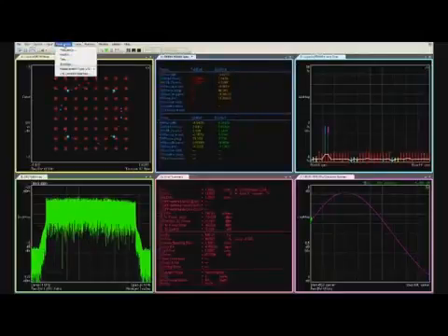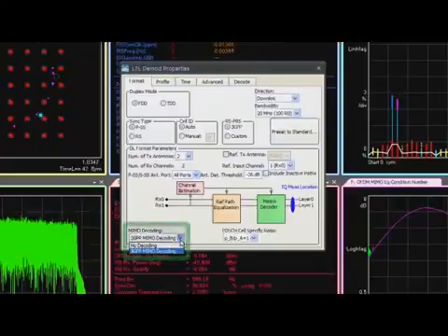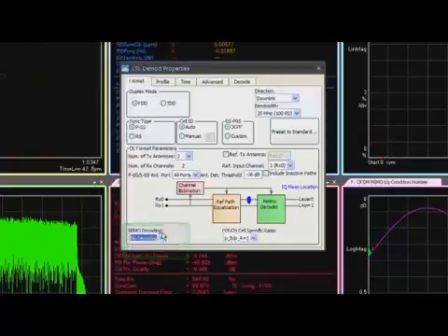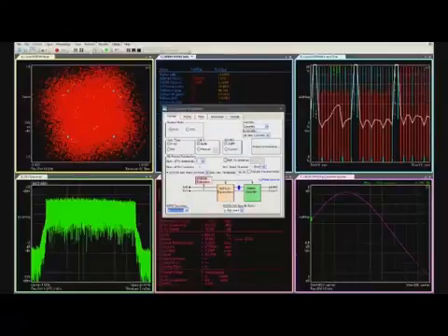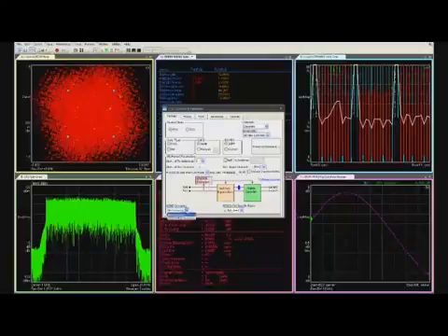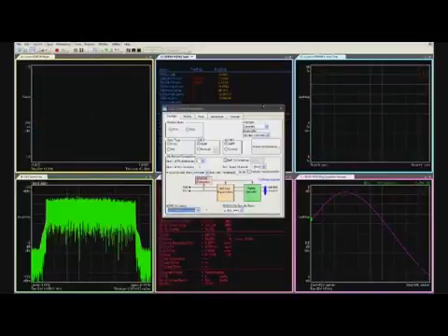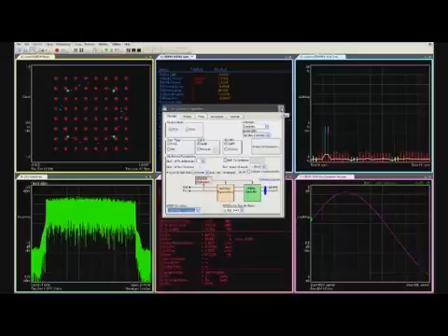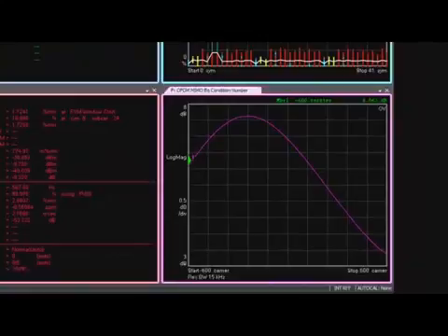For example, if matrix decoding is disabled in the demodulator properties dialog, signal demodulation will fail completely. This only works with codebook 0, since an unimpaired signal with codebook 0 contains no cross-coupling. Another indication of impairment is the large magnitude of condition number shown in this graph.